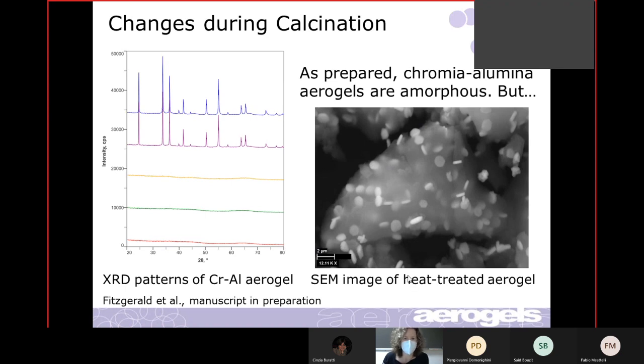In the work that we're doing with catalytic aerogels for automotive pollution mitigation, we need to have materials that could operate at a high temperature because this would be something that could potentially be used in the automotive exhaust stream of an automobile or something that has an internal combustion engine. And it's okay if a transformation occurs and then is subsequently stable if the material still operates, has the properties that you need. It's not okay if we're going to see an overall decomposition.